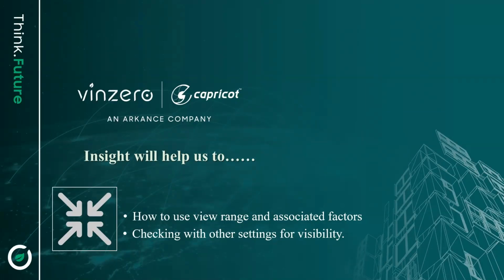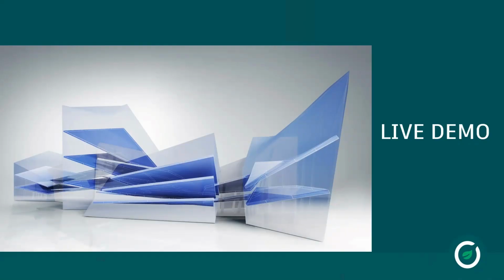In this insight, we will cover how to use view range and its associated factors so that we can view objects particularly in our plan views. In the view range, we have options for associating its level and view depth, which helps us view objects at particular levels, say ceilings or floors, which are also interlinked with disciplines. So let us move on to the live demo.